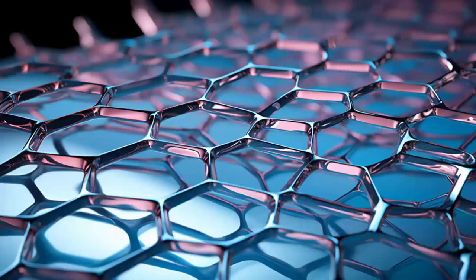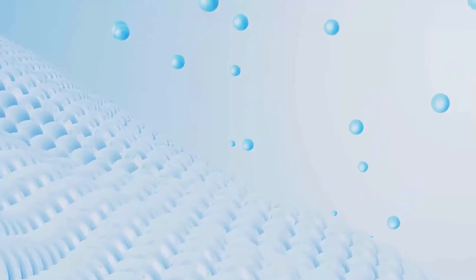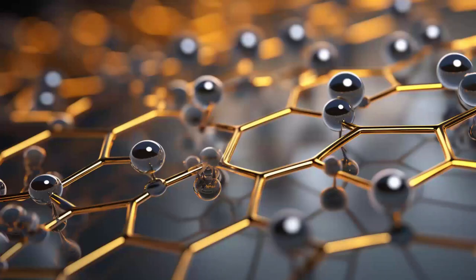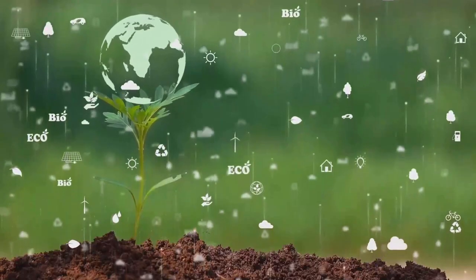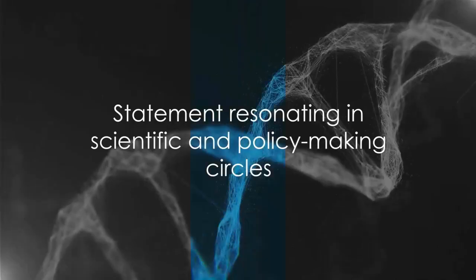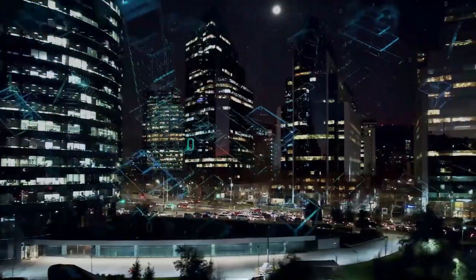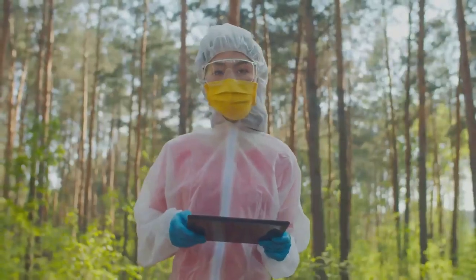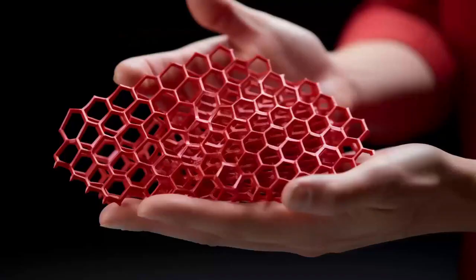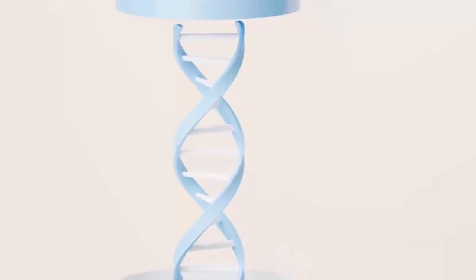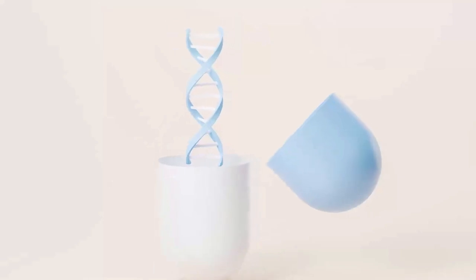One of the most prominent applications of nanofabrication is in the electronics industry. The ongoing demand for smaller, faster, and more efficient devices has driven the development of nanoscale transistors, integrated circuits, and memory chips. Techniques such as photolithography, electron beam lithography, and nanoimprint lithography are employed to produce these components with extreme accuracy. For example, modern semiconductor manufacturing relies on nanofabrication to create transistors that are only a few nanometers in size, which is essential for the continued advancement of Moore's law.